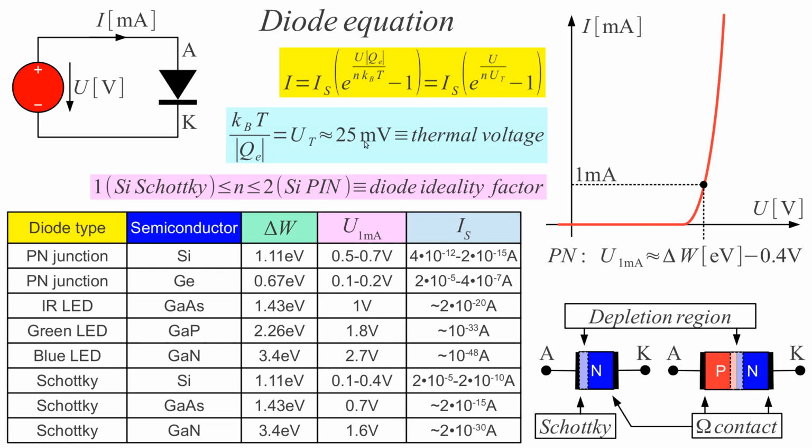And we see that for different semiconductors, we can build a rectifier as a p-n junction. A p-n junction joining, so doping a crystal of silicon partly p and partly n. So here we have an excess of electrons. Here the majority of carriers are holes. In between we have a thermoelectric contact voltage that builds this depletion region, where charge carriers are depleted. This is actually an insulator because holes moved in the p region and electrons moved in the n region.